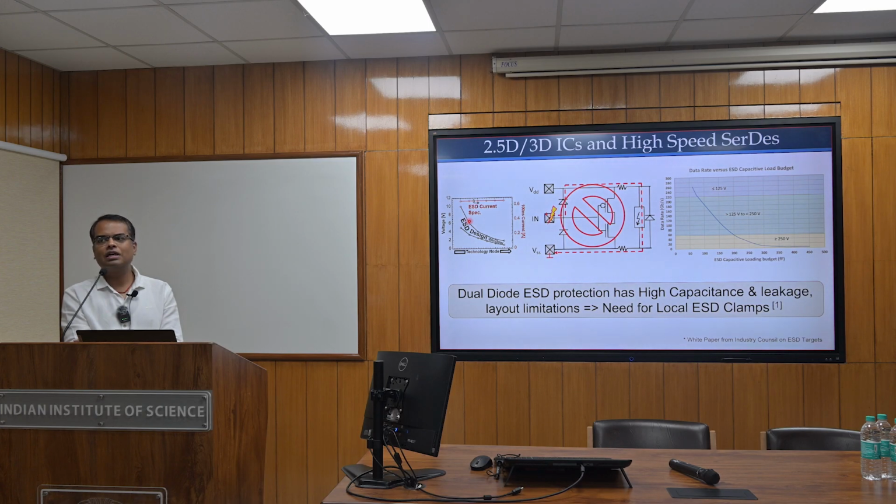Since the most vulnerable part in the IC is the gate oxide, and as you know, in order to improve the performance of the MOSFET, the gate oxide is becoming thinner and thinner, the breakdown voltage for the MOSFETs is also falling as the technology node scales.